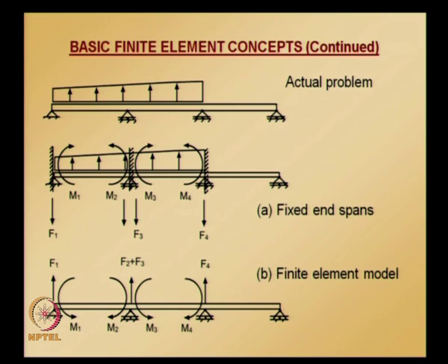Such a structure will experience moments and shears in the loaded span alone, and that is, each loaded span is an independent fixed end beam. Exact solutions for these fixed end beam problems are easily available in elementary mechanics of materials books.